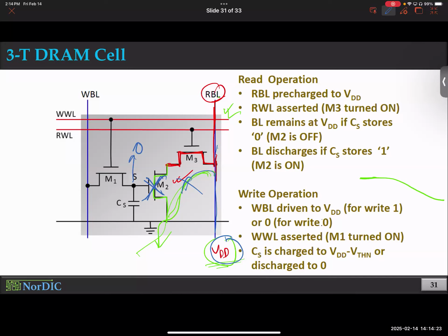Pitch, if you see the numbers, you can Google Intel 14 nanometer metal pitch. Just Google. It's public knowledge now because it's an older technology. 3 nanometer may not be so. But the older technologies, you can just Google it and get the numbers. And you see the number. Oh, between 2 metal lines, you need to have that much separation. So when you introduce new metal lines, that's immediately a challenge.